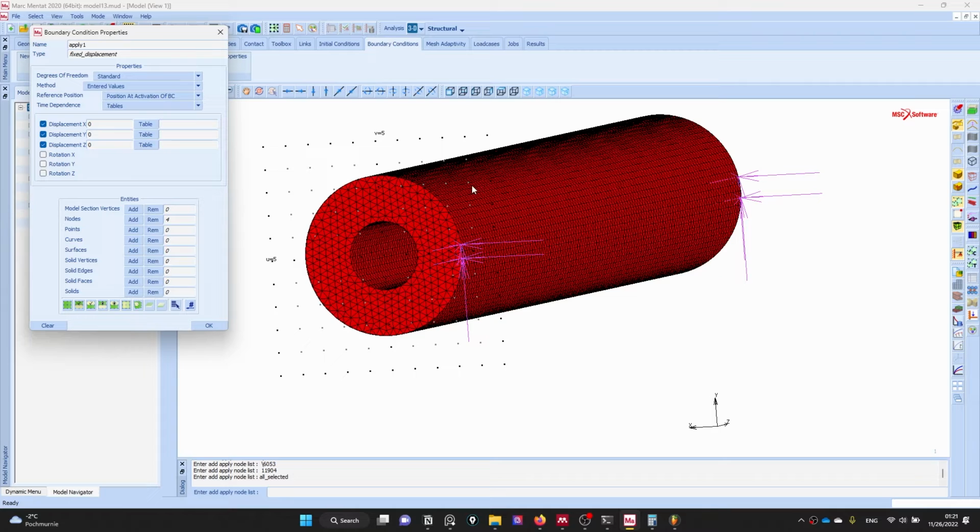I cannot fix the circumferential edge, because when I apply the pressure, our cylinder will expand. If I define the fixed boundary condition from the circumferential edges, this boundary condition will not allow for expanding. Therefore, higher hydrostatic pressure will be encountered.